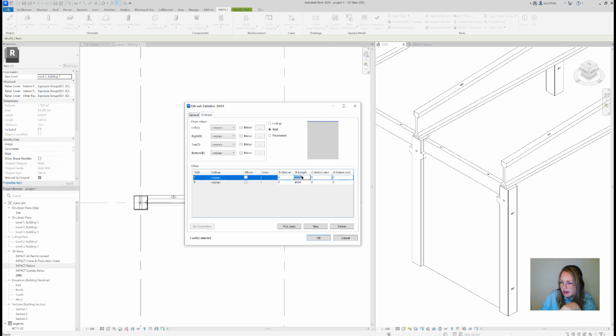You're basically doing a kind of a recess. I have some numbers here which are going to help me define the recess that I need for the corbel, and you already see it here in the top. So we're adding an end cap on the top from left, and you're gonna need the same because there's another corbel on the other side.